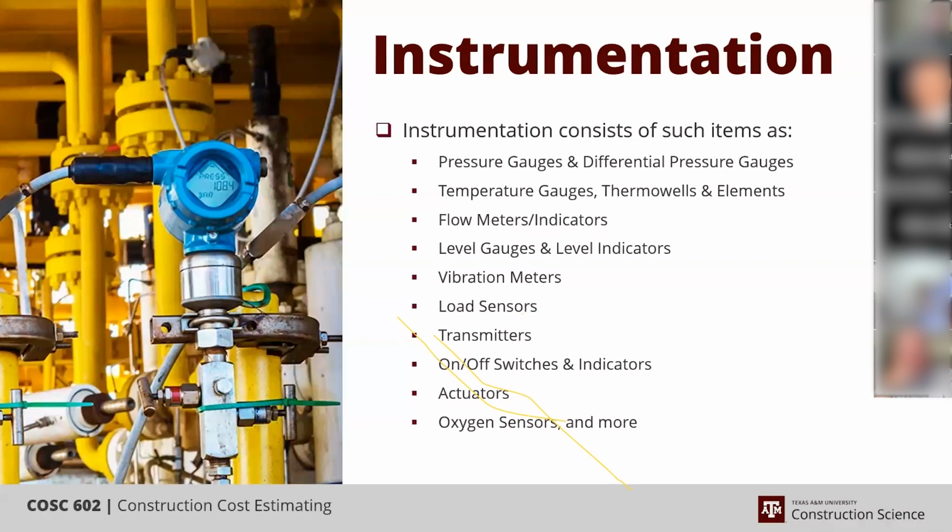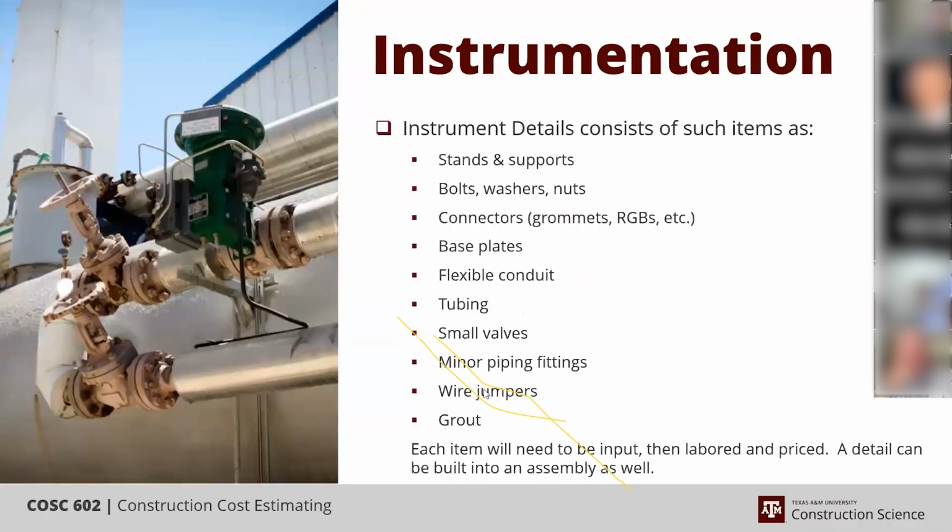And then on top of that, you've got software. We'll talk about that here in a second. We also use a lot of the load cells for the rail cars that we load, because there are federal law requirements that you can't exceed certain weights on rail cars when we transport chemicals. Yeah, good example. And so they're all tied into the control system overall.